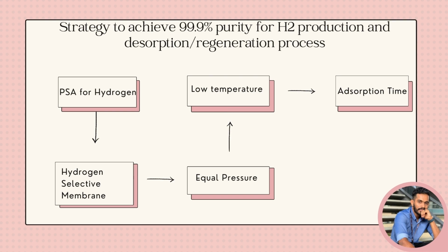So for the low temperature, the process is called cryogenic separation, where purified hydrogen is derived from syngas. The difference in boiling points helps to separate the different compounds found, which leaves the hydrogen in gas phase while the rest is condensed.